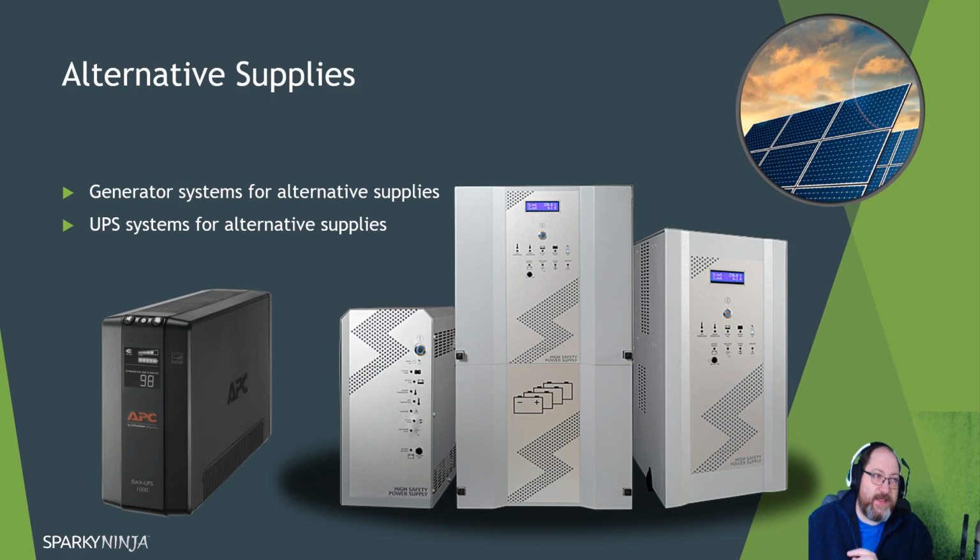Similarly with alternative supplies: UPS standby supplies for IT, medical locations, or solar photovoltaics. Now, if you've got solar photovoltaics, you've got a supply source that, even if you turn the main isolator off, if the solar radiation is there, you're still going to have a presence of source coming through to the inverter. So there'll be another isolator on the AC side of the inverter, or you'll have a big label on the fuse board that says two sources of supply. These are the other characteristics you need to be aware of. Similarly, you'll have DC cabling coming in, which will be energized. So you may need to label that up, in case someone turns it off and then thinks that equipment is dead.